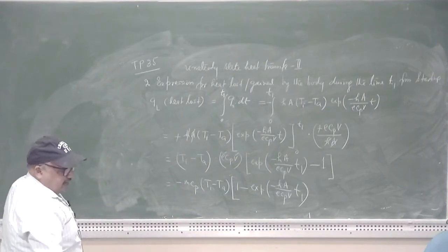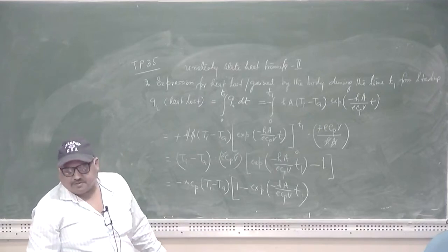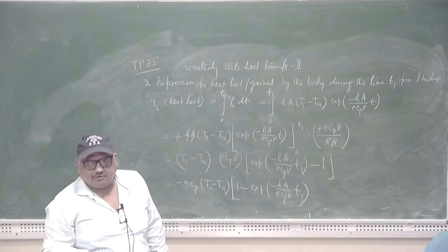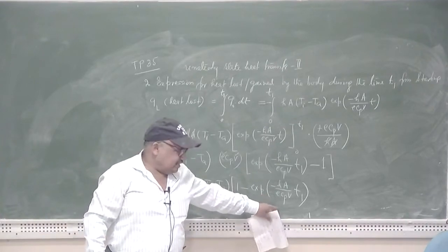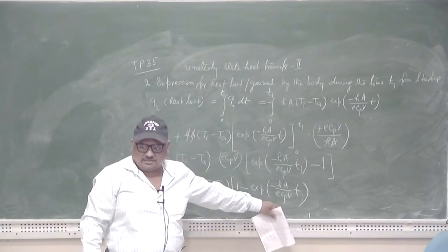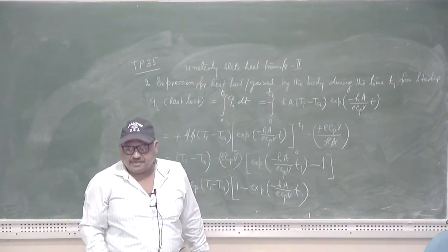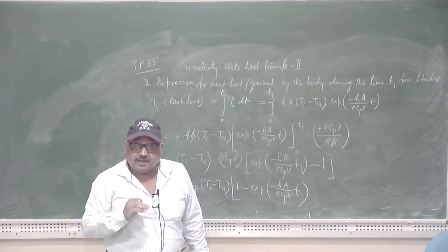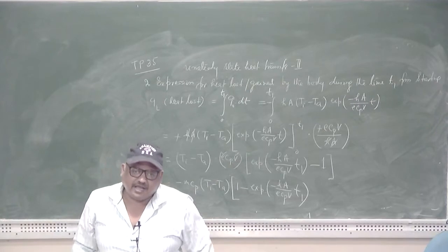If you further extend this equation in terms of the dimensionless number, then referring to the previous class, this quantity which is enclosed in the parenthesis associated with the exponential term can be represented as a product of the three dimensionless numbers, that is the Biot number, the dimensionless position, and the Fourier number.